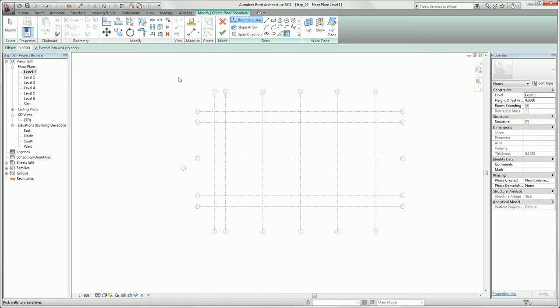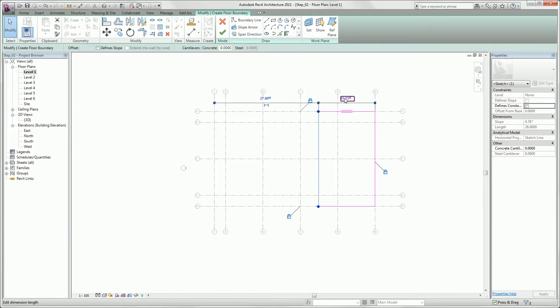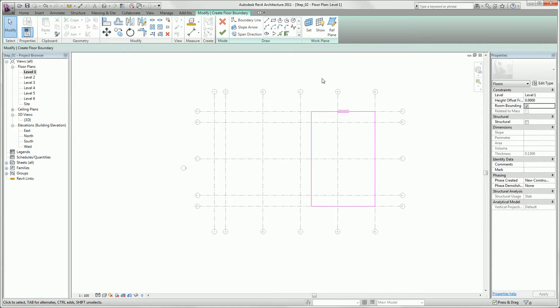We select the rectangle tool and we draw a rectangle from the right top corner to the left side. We see here 3 lock symbols, which give us the possibility to attach the boundaries of our element to the grid lines. We click the lock symbols. Now we move our left boundary, and we can use here the temporary dimensions and put in here 17 meters. Now we can finish the edit mode.